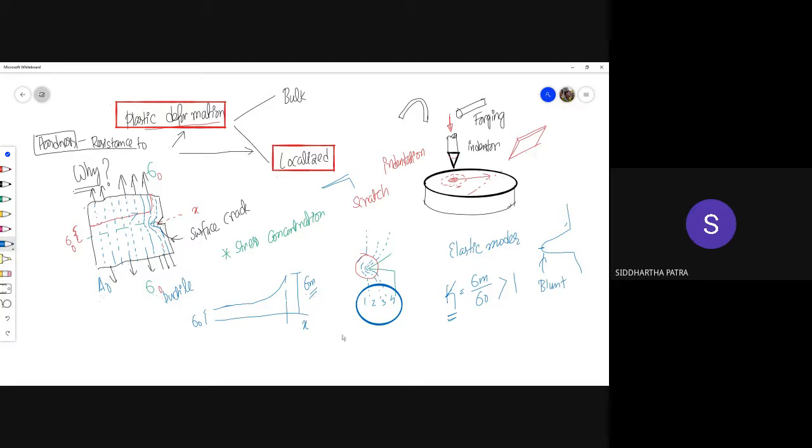What happens if the crack starts propagating for a brittle material? You have a larger crack, so more area is absent from bearing the applied load, and this continues, becomes kind of perpetual, and eventually leads to fracture of the specimen. For extremely brittle materials such as glass, that's a severe condition.